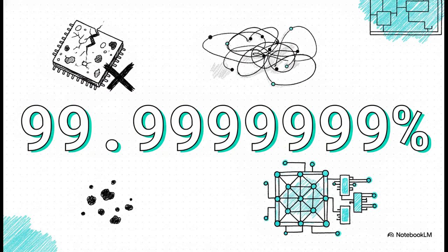Okay, that sounds great, right? We have our silicon. But here's the catch. This new metallurgical silicon is only about 99% pure. Now, in the everyday world, 99% is an A+ grade. You'd be thrilled. But in the microchip world, 99% is incredibly dirty. To make computer chips work without crashing, we need what scientists call nine nines purity. That means our silicon must be